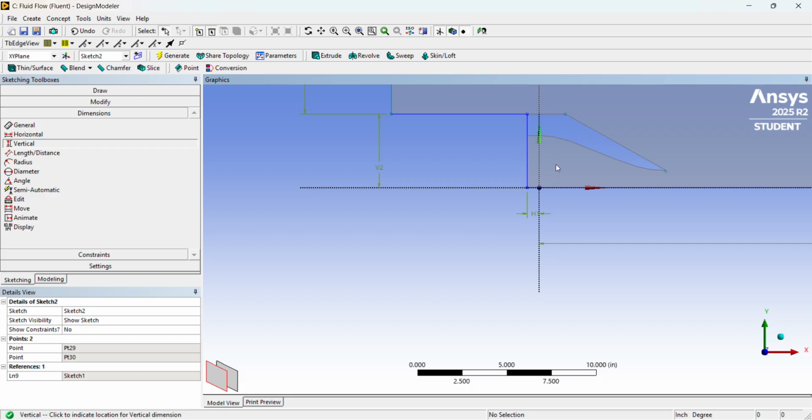So for the horizontal, we can do one thing. Yeah. So you can just go back and try to measure this. And if you are able to measure this, I think it will come around 2.1108. I have already done the measurement. So if you go into SolidWorks and start measuring from here to here, you will be able to get the exact point. And let's dimension this.